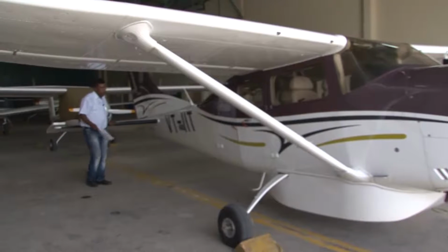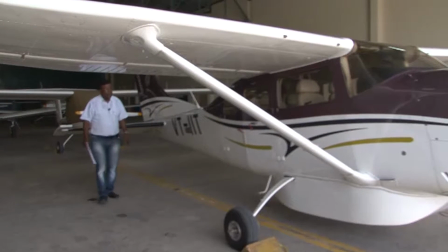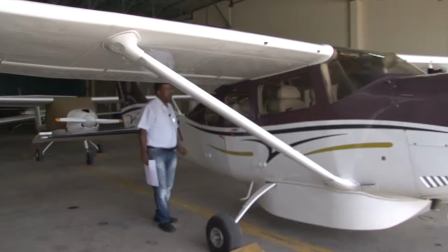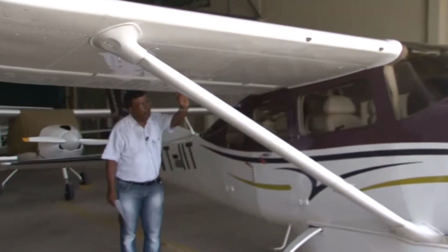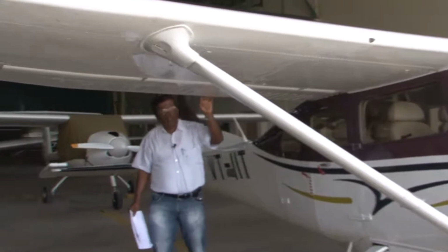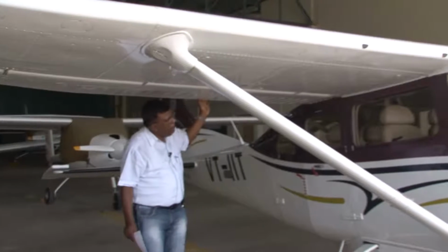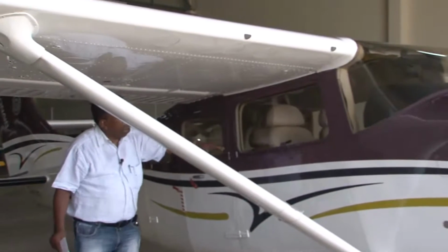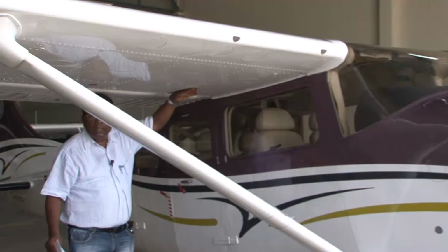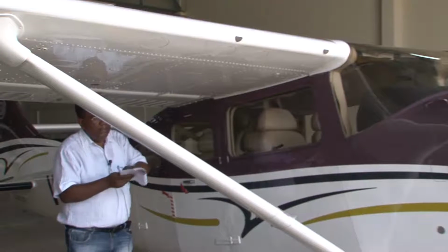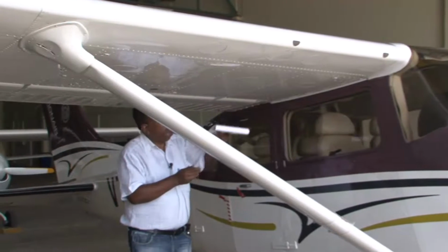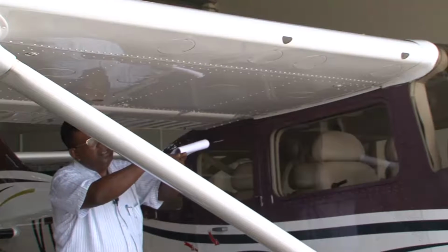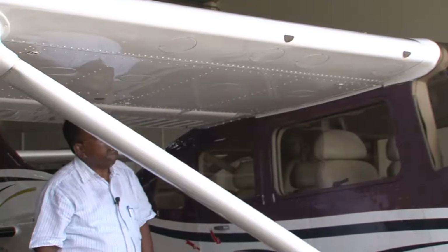It is also important to see what will be the CG location. We will show you where the CG location is when you cover the stability part of it. Again, coming back to the wing, there is another important thing you should realize, whether the wing is parallel to the fuselage reference line or the wing has a setting angle. That is, how this wing is mounted, parallel to the fuselage line, or it has been given a setting angle, which we call wing setting angle.